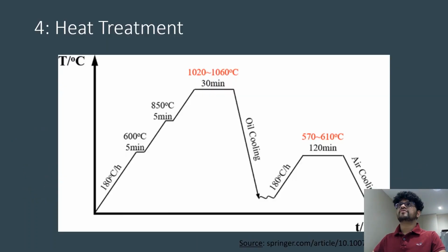The shaft, now finalized, is reheated to 1200 degrees centigrade in a quench annealing furnace, followed by rapid cooling in oil or water. The material is tempered around 600 degrees centigrade to ensure the material structure is in accordance with specifications. Shafts are now transported to a cooling bed and prepared for further processing.